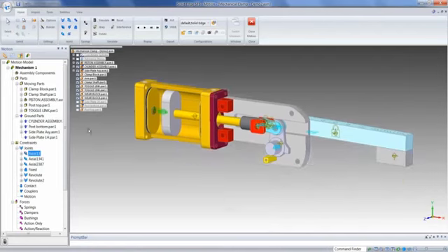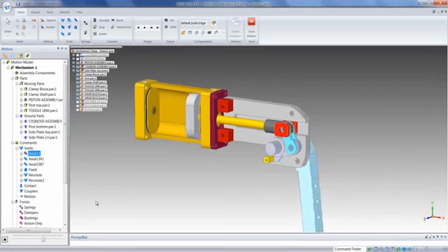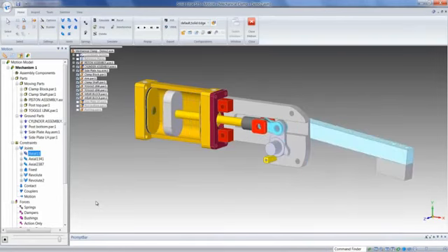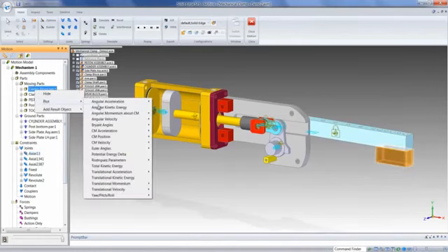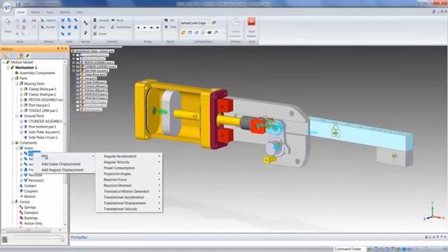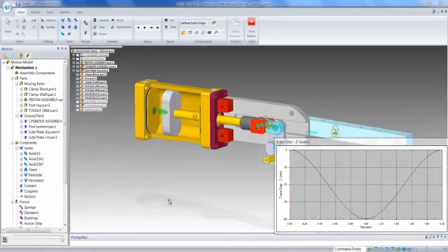If we go ahead and apply and then run our simulation, we should see our changes. We can plot characteristics for any part, and we can also plot characteristics for any joint. In this example, we'll plot the translational displacement for the actuator simply to verify our input was what we'd expected it to be.